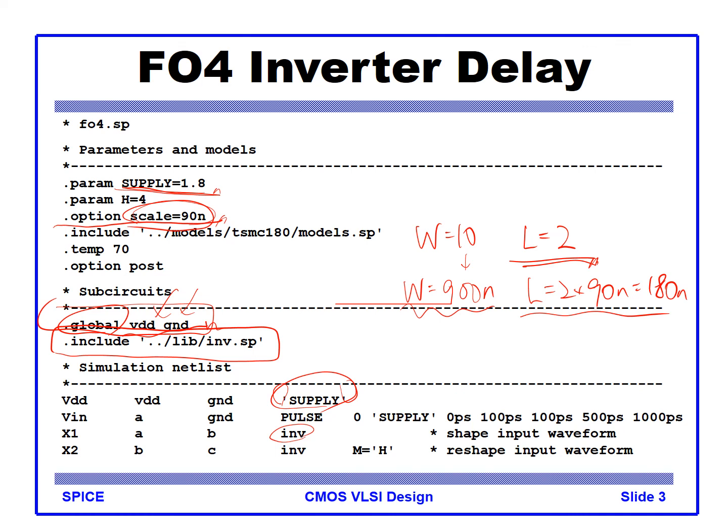So let's say for example sub-circuit A, B and C. Inside, it will have a VDD and ground node here, and another sub-circuit with VDD and ground node here. If the name is the same, then all these are connected if you define it globally like this.